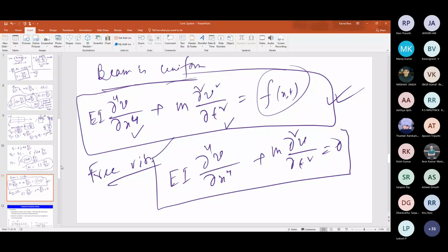So you have to analyze this equation to find out the natural frequency and motion. Because we do the free vibration analysis, right? Undamped free vibration, m x double dot plus k x equals 0, and then you substitute the assumed solution and obtain the eigenvalue problem and solve the ensuing equation to find the eigenvalues, and then you find the eigenvector, right? That is done for the multi-degree-of-freedom system. So a similar approach will be adopted here to find the natural frequency and the motion.